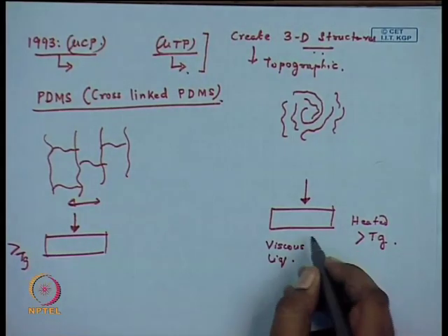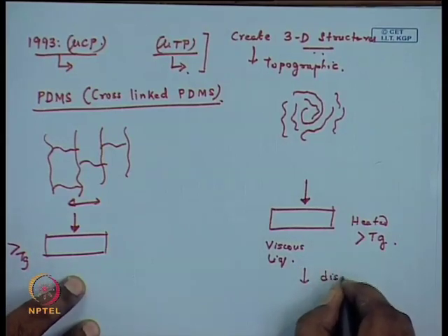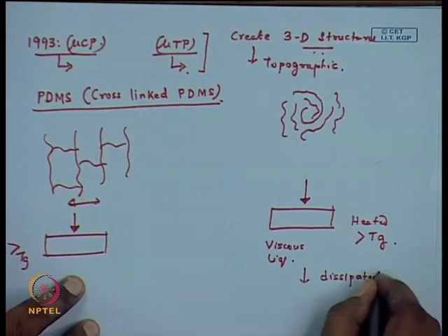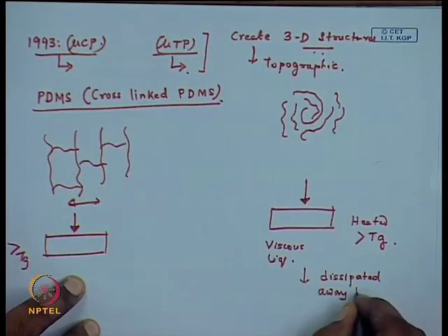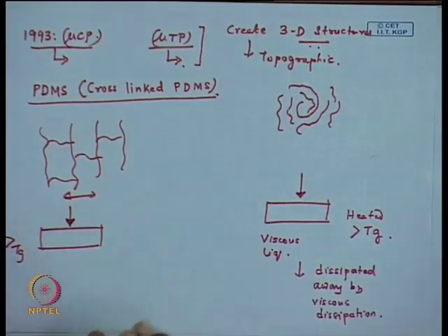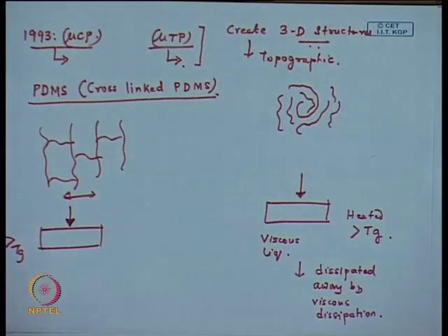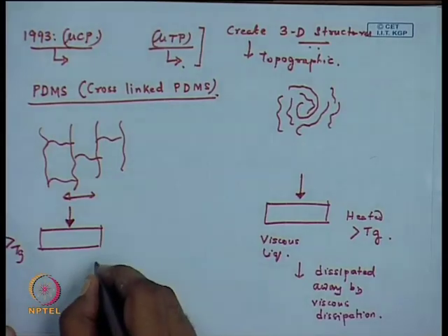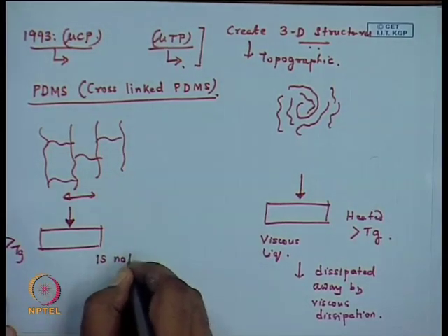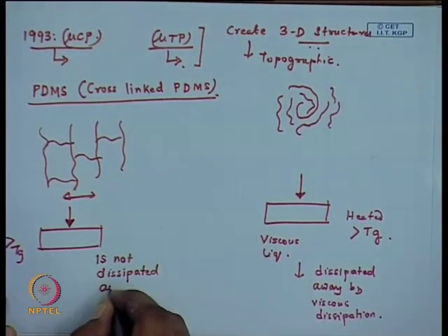So, if you apply the force, the deformation energy is dissipated away by viscous dissipation. However, here if you apply a force, that definitely supplies thermal energy to the molecules, so they are free to move, but the energy you are giving remains, it is not dissipated away,